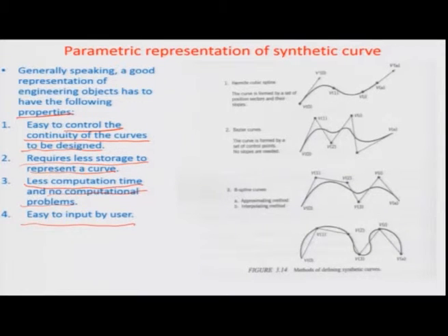In line with this, there are certain very nicely defined curves which have emerged to define the basic element of such synthetic curves, a repetition of which in 3D space would lead to the whole contour or the whole profile sometimes. So, the first representation is known as the Hermite cubic spline representation. It is formed by a set of position vectors and slopes.